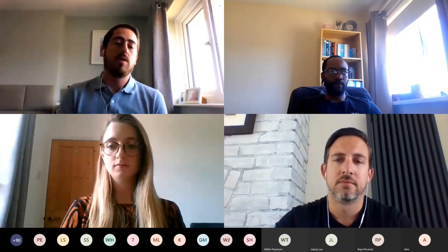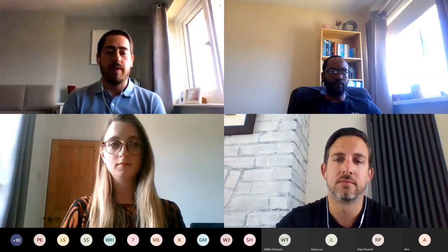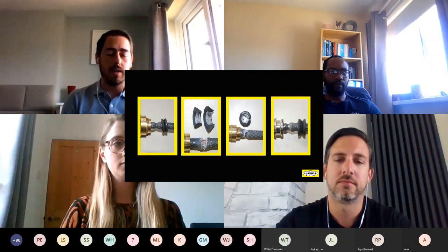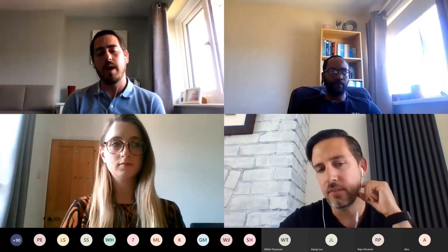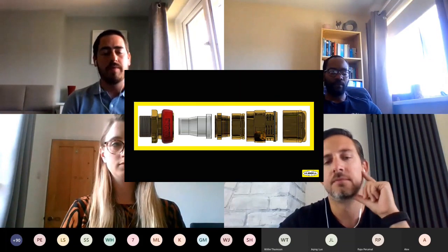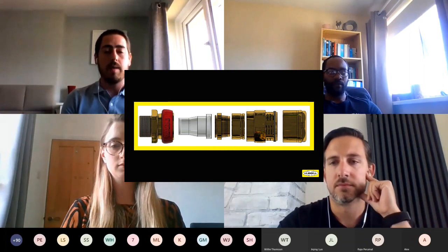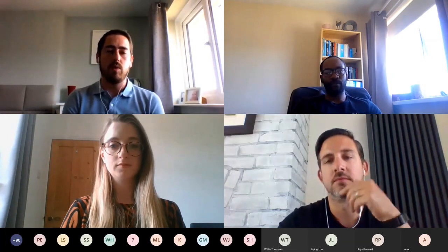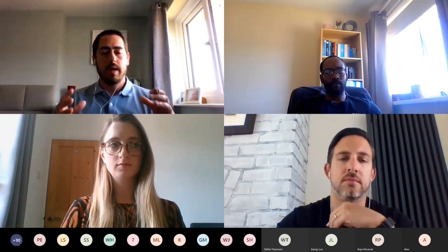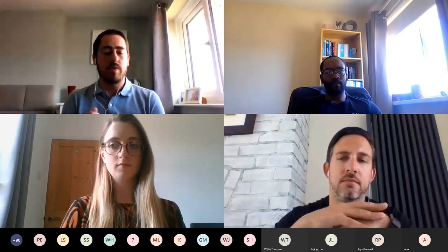This is a seal that was designed to reduce the effects of cold flow. Again, this is your EXD seal in this particular type of gland. And then we have barrier glands, and we have 2 different types. One is a potted gland, where we can either use the express resin or a 2-part putty. That's where it's set around the individual cores and gives you protection around the individual cores rather than the cable doing that.